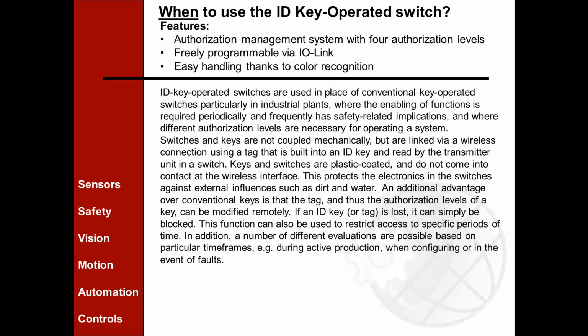So you have a degree of protection between your front panel and your electronics inside. So in other words, dust and water are not going to get in and penetrate your panel through these key switches. And everything happens wirelessly. I think with key switches and especially with card readers and that sort of thing, you do have a degree of penetration that you have to verify with those. So these are IP65 rated.